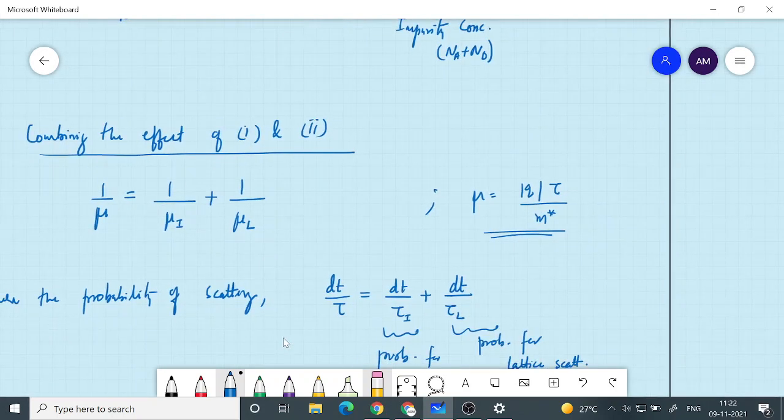You remember the energy band structure that we had. We had this curvature like this, whereas for the holes we had a curvature like this. This is the valence band and this is the conduction band. If you have higher curvature, that means smaller effective mass. Smaller effective mass, higher mobility. Those concepts are contributing to the difference in mobility for electrons and holes.